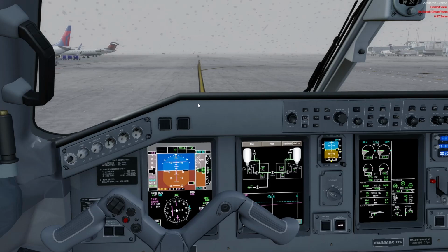The fear is that in some areas it would become even colder, and some ice can accumulate, or when we build up speed and the pressure around certain points in the airplane reduces, the temperature also reduces, and we can still accumulate ice even though the residual temperature might be as high as 10 degrees, or in this case 3 degrees.